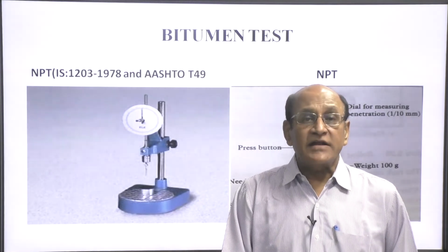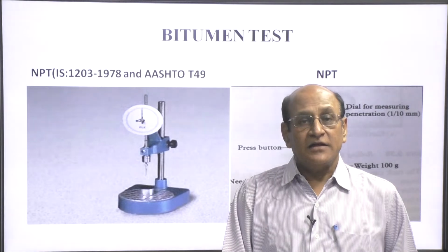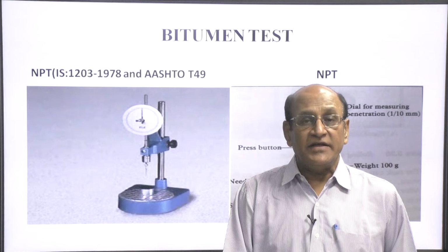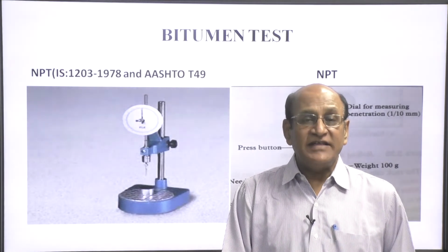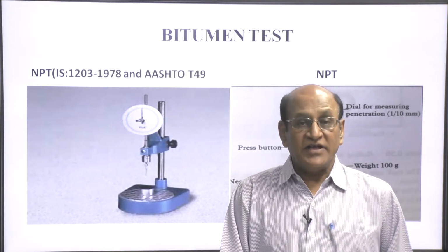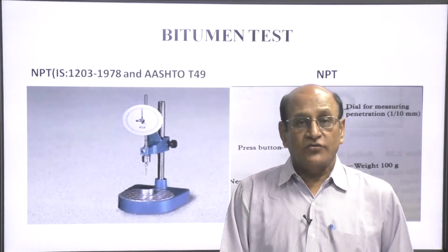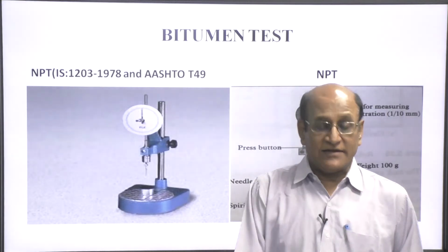But now all Indian companies like Indian Oil Corporation, HPCL, BPCL have changed, and now the name of bitumen is based on the viscosity grade, VG grade bitumen, like VG 20, VG 30, VG 40. So the bitumen grading has changed, but this is the very basic test.